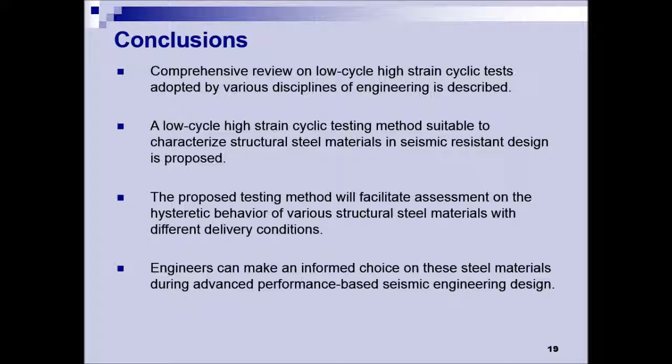In this study of hysteretic behavior of structural steel materials, a comprehensive review on low-cycle high-strength cyclic tests adopted by various disciplines of engineering is described. A standardized low-cycle high-strength cyclic testing method suitable to characterize structural steel materials in seismic resistant design is proposed. This will facilitate assessment on the hysteretic behavior of various types of structural steel materials, and engineers can make an informed choice on these steel materials during advanced performance-based seismic engineering design.